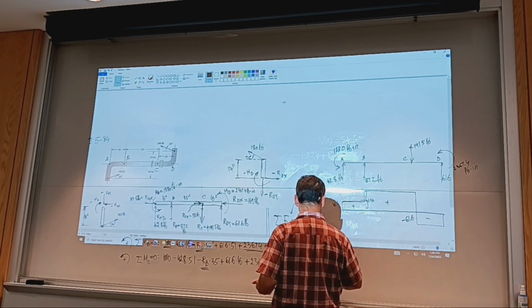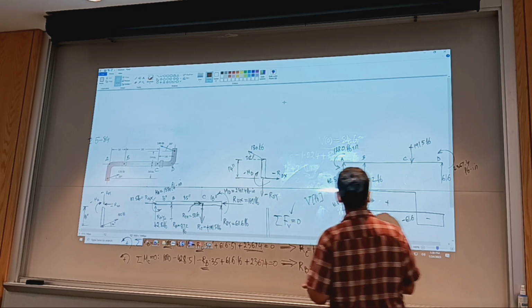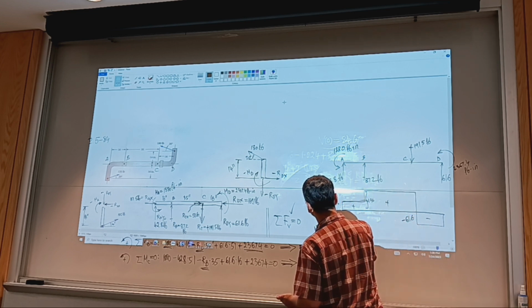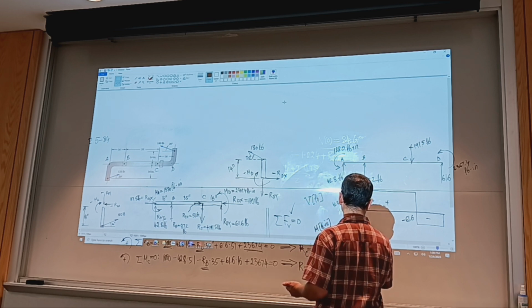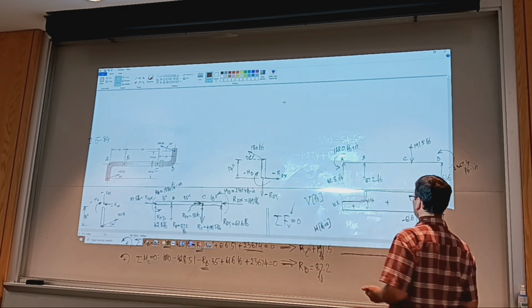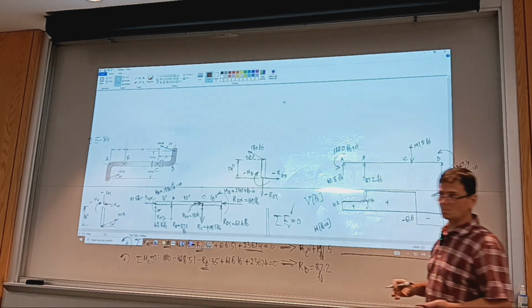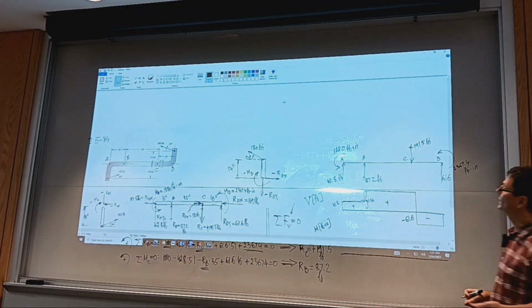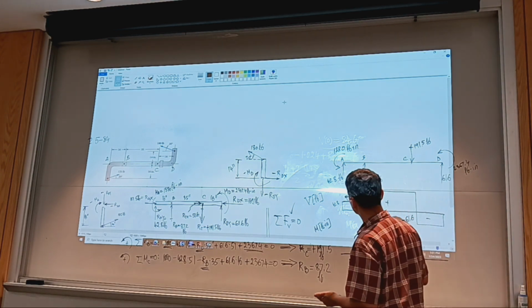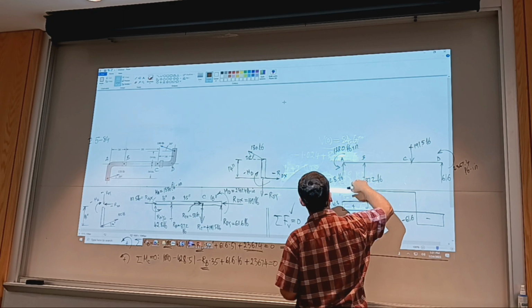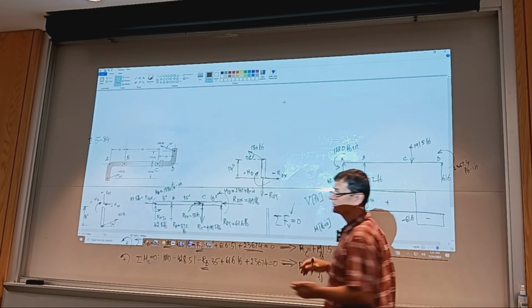So pounds and pounds. Let me draw the moment now. Moment diagram, moment in units of pound-inch. And I show the neutral axis. And let's not forget we have external moments now. So the diagram begins with a drop, because this is counterclockwise.